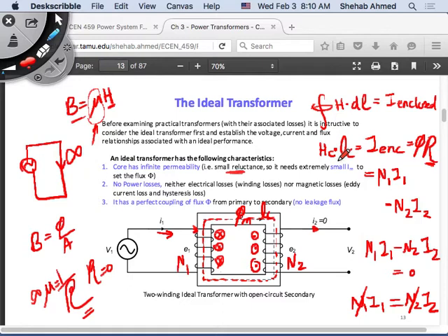This is just an ideal representation of the transformer. So here I completely ignored any need to set up this magnetic flux. I set up this magnetic flux for free, basically, which is not true, right? So we will look at what the real equation is versus the ideal transformer. But we will use the ideal transformer approximation a lot. What the ideal transformer tells us is that ampere turns in the primary is equal to ampere turns in the secondary.